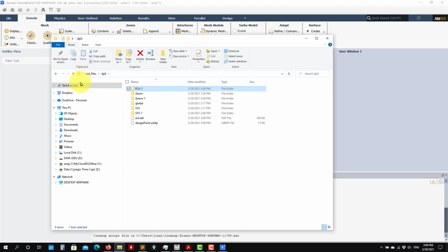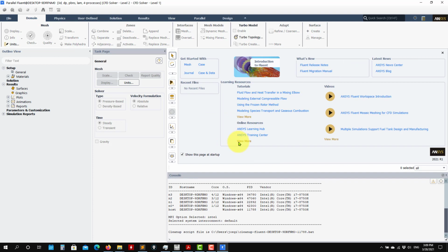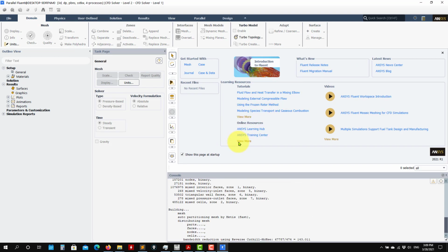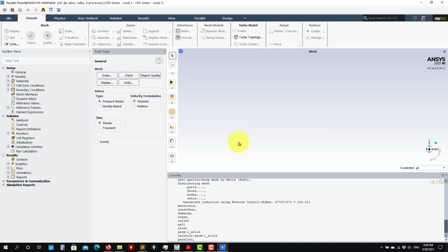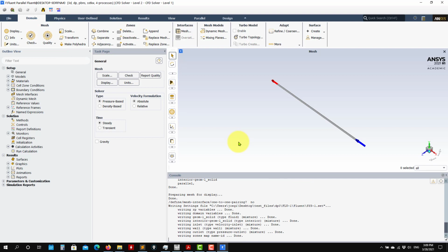What I say is that I don't like to launch Fluent within the Workbench because it starts to save backup files, a lot of information, and sometimes it's difficult to move in this directory hierarchy. So it's better to go outside of this Workbench bubble. So most of the time, just use Workbench to generate geometry, mesh and convert it. That's all. Okay, so we're here.